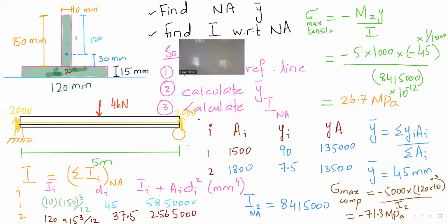What will be the stress at the point? What is the torque? Torque multiplied by the radius, which will be 50 times 10 to the power minus 3, divided by the same polar moment of inertia, because the polar moment of inertia is for the same object. 1.2723. What is your question?